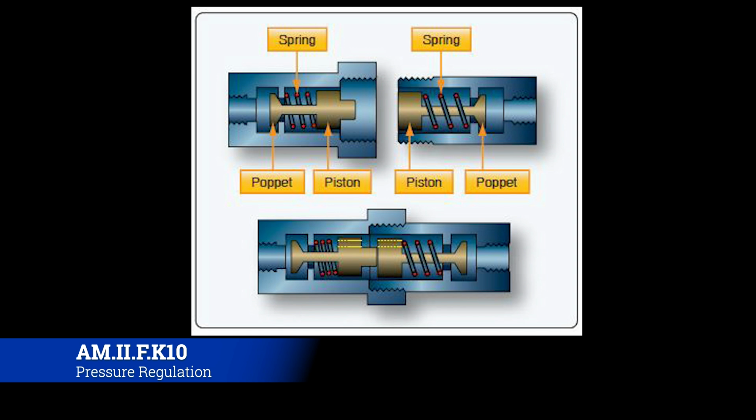We used these pretty extensively in the Army on the OH-58, because if we ever had to do any sort of flight control work, we had two hydraulic quick disconnects on the right hand side of the helicopter that we would disconnect. Then we would hook up our aviation ground power unit, or AGPU, directly to the system, pressurize the hydraulics, and go on from there, troubleshooting whatever issue we had.